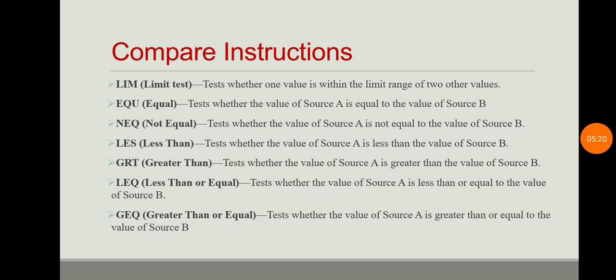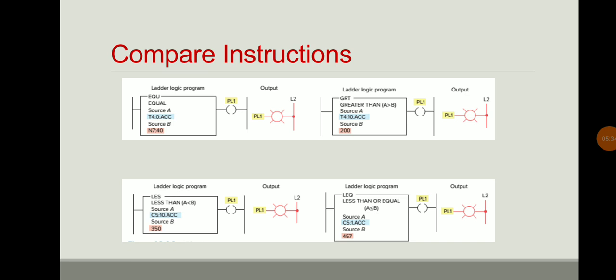These are the basic compare instructions: limit, equal, not equal, less than, greater than, less than or equal, greater than or equal. These are the basic instructions which are available in PLC software. These are some basic small examples. We have to see what is equal.